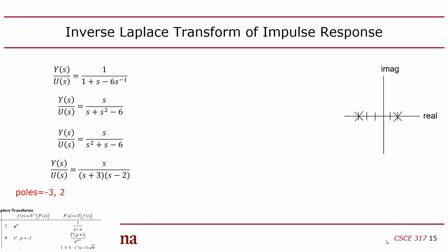So what ends up happening is, there's a couple things we can do. What do we do from this point? How do we know it's not stable? So one option is to calculate the impulse response, but we want to see it in the time domain. We want to see what happens when we hit this with an impulse, right? So to do this, we take this transfer function, multiply it by 1, which does nothing, but then calculate the inverse Laplace transform. We've got to get this back in the time domain, right?